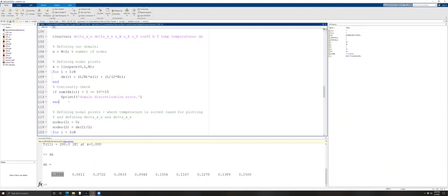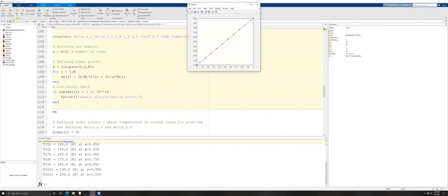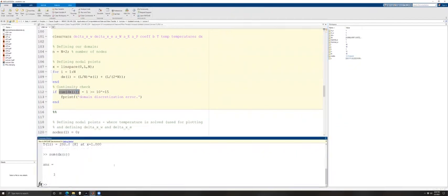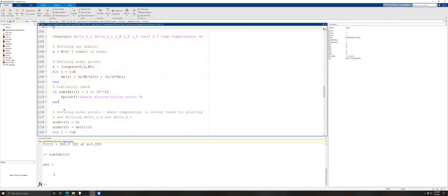So I said the sum of dx, i.e. we take the sum of all the lengths of our control volumes, less 1. This should be 0. And if it's greater than 10 to the minus 15th, then we have an error. Just because it's hard to think about absolutes in a computer. So if I run this, no errors are thrown. That is, if we take this value, sum dx, it is indeed equal to 1, at least the way it's formatted.